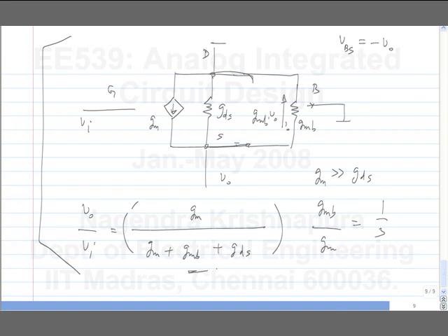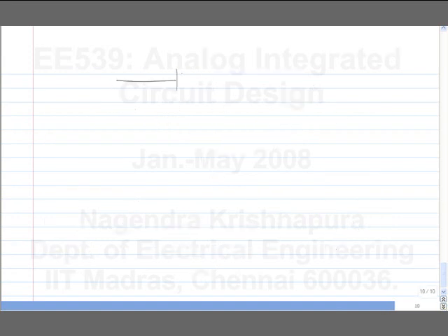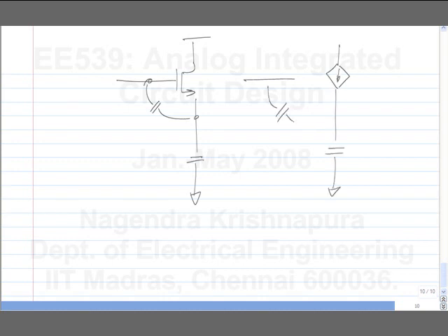So what happens if you load a common source amplifier with a capacitance? Have you seen this circuit before? Yeah, this was also in assignment 1. So you have the capacitance of the transistor and this. The assignment 1 asked you to calculate the input impedance of something like this, right? So what was the result? Negative resistance. So one of the risks of using a voltage follower is that on the input side you can see a negative resistance. Okay, so you can have an oscillation problem, a stability problem, with a voltage follower.